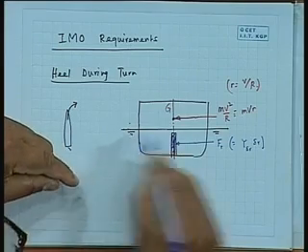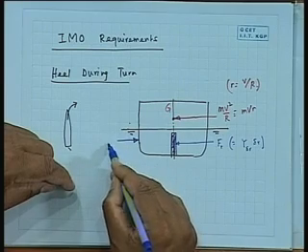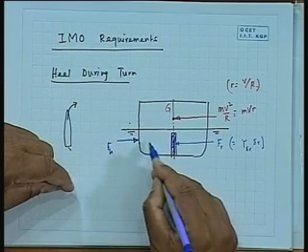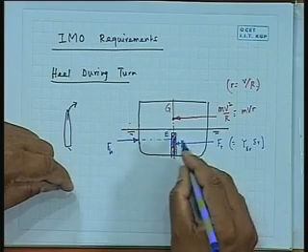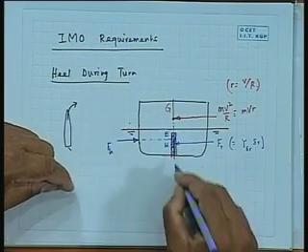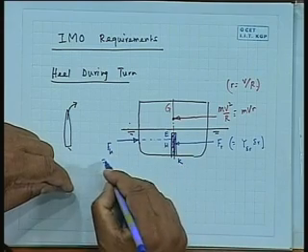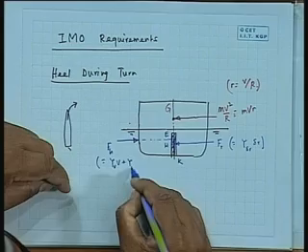And as the ship is turning, obviously it is going to produce a reaction force which is Fh. Maybe it is acting at a point, we call it E here, this is H here, this point, this is G here, this is keel here. Fh is equal to, in a steady turn, Y_v v plus Y_r r.